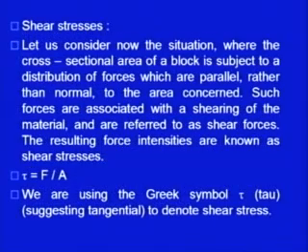Now the second type of stresses are the shear stresses under the direct stress component. Let us consider the situation where the cross-sectional area of a block is subjected to a distribution of forces which are parallel. Now, you see the force application is not along the same axis. It is a different axis, meaning there are two parallel axes, and at this point and at this point two different forces are acting. So, definitely there is a plane which is shearing the object at the contact points.